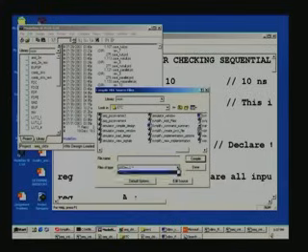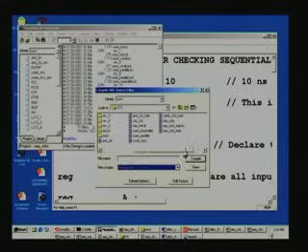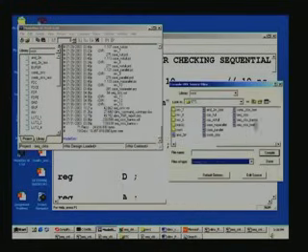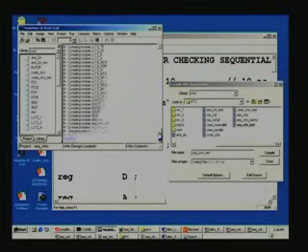In fact, we do not need that also, because it can be Verilog itself. So, after all what we need is only the sequential circuits test, the test bench. So, we will just double click on this and watch what happens here in this window. When you double click here, you see it gave a big list, and I will read it for you.